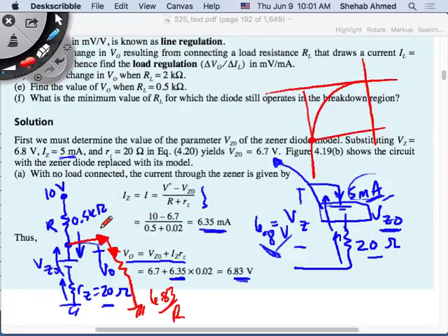So I will have a current, let's say 2 milliamps. We will look at their numbers, but let's say 2 milliamps. So what happened to the current that's flowing in my Zener? It decreased by 2 milliamps. So I have to go back here and decrease by 2 milliamps, and I will have a new V Zener. I will also have a new VZ0. How far is this VZ0 from my original VZ0?